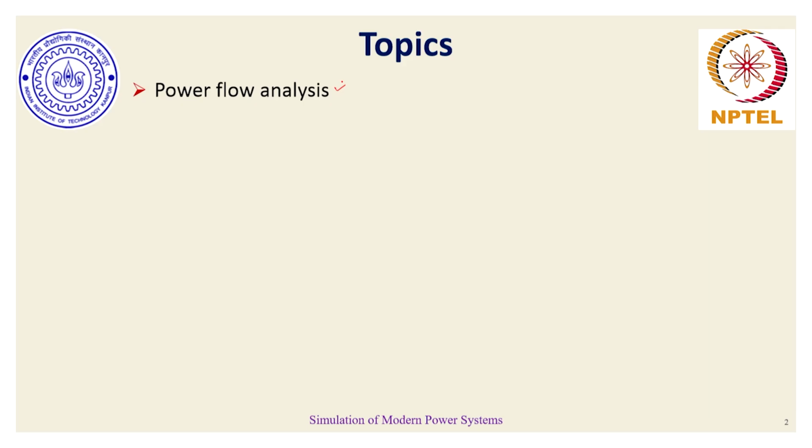given three-phase power network under steady-state conditions. This will be followed by a well-known, most commonly used tool in the power industry, known as contingency analysis, also called security analysis, which lets the operator know what happens in case of a contingency. We define contingencies as the set of events that can happen in time during the course of operation and may be detrimental to the overall operation, security, and stability of the power network.